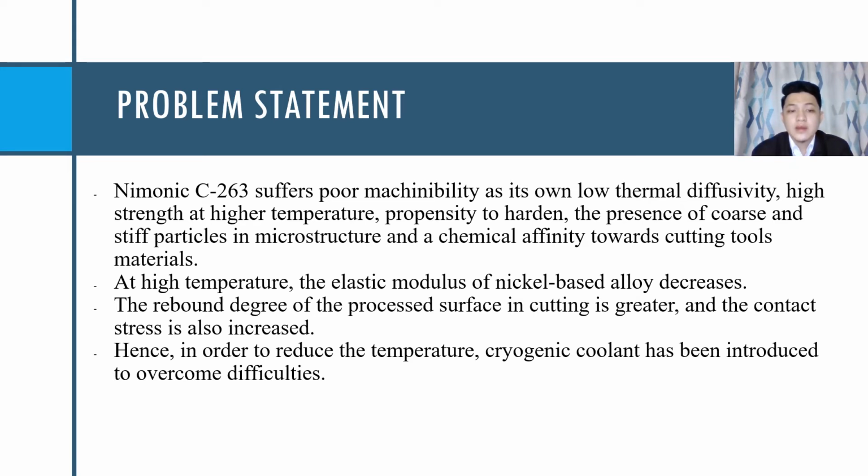Other than that, at high temperature, the elastic modulus of nickel-based alloy decreases. The rebound degree of the processed surface in cutting is greater, and the contact stress is also increased. Hence, in order to reduce the temperature, cryogenic coolant has been introduced to overcome the difficulties.